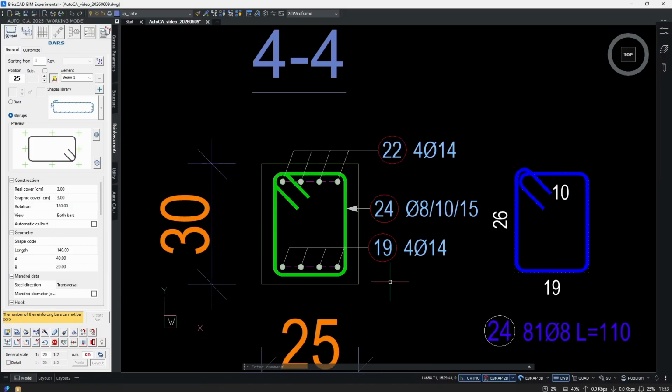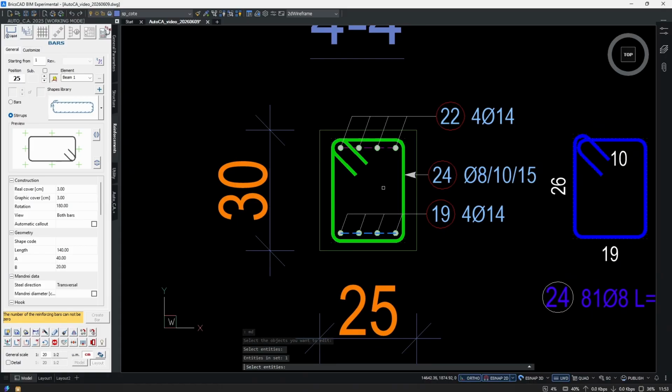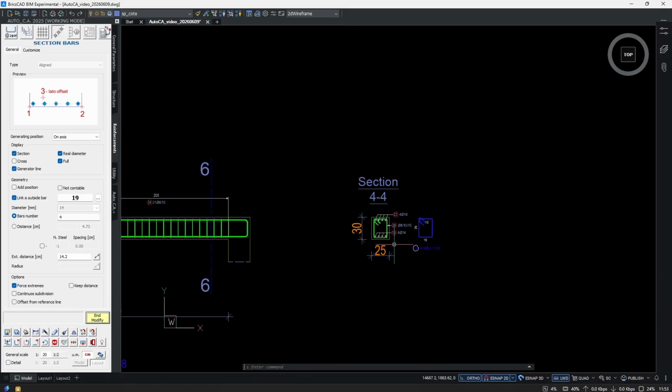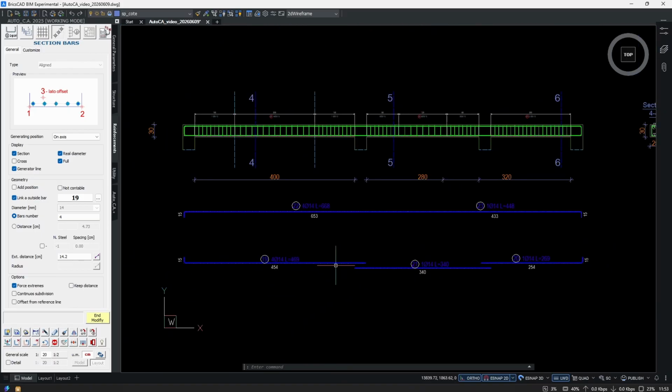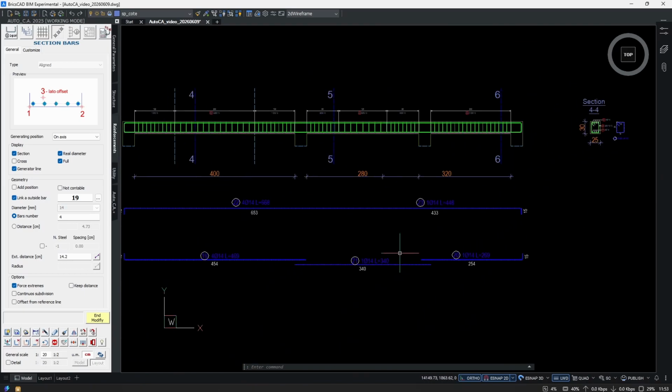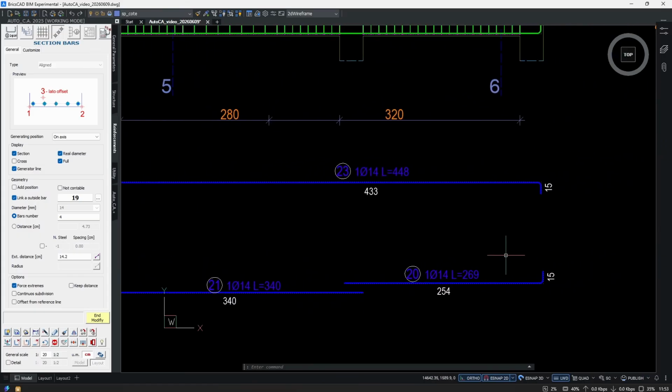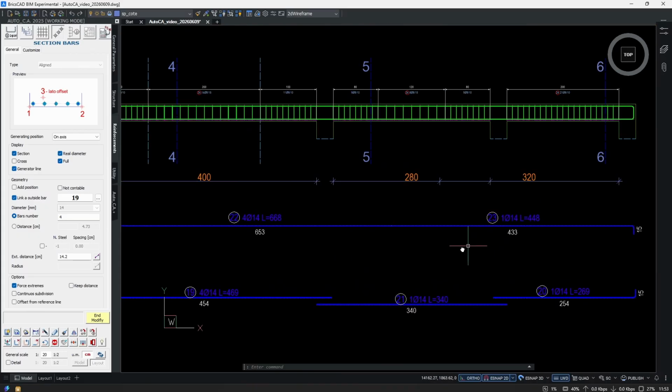And what I want to show you is that you can assign the same bar section distribution to multiple outside bars. So if you don't want to create physically 3 different cross sections, but still you want to distribute all these bars to avoid inputting manually the quantity, then you can do this.